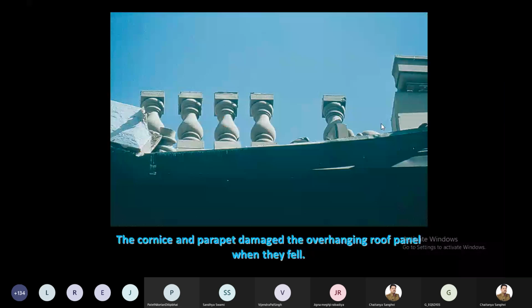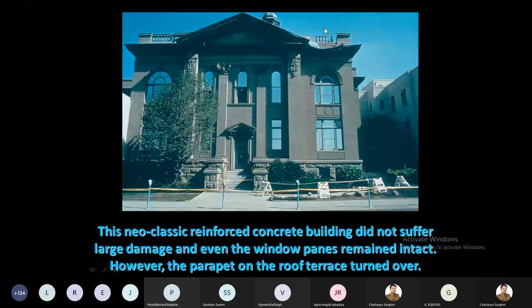For example, these are the gamlas which are generally used for decorative purposes on the parapet, and because of the shaking, if this is not properly fixed, it may fall. Now imagine this is a very beautiful building, and when you come out of this building during an earthquake, suddenly something drops on your head and you die. Such things should not happen, right? This is the non-structural failure.